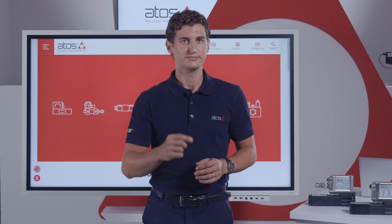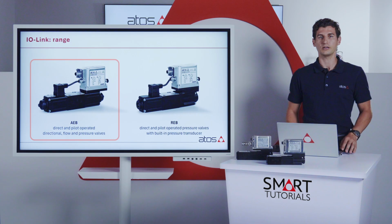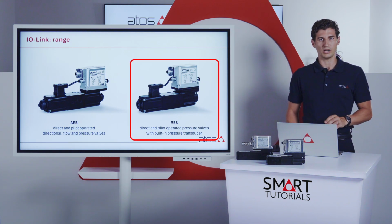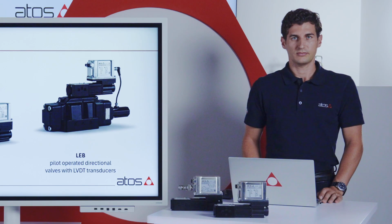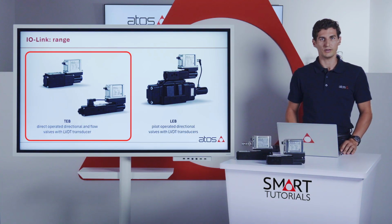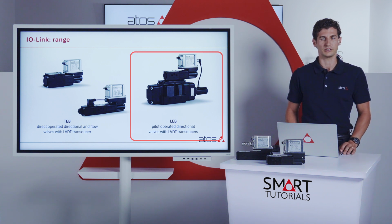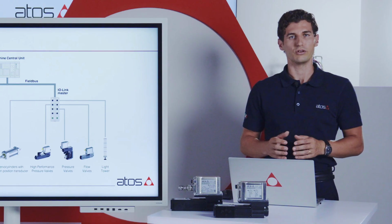So, let's start. The IO-Link communication interface is available for direct and pilot-operated directional, flow and pressure valves, and pressure valves direct and pilot-operated with built-in pressure transducer. IO-Link is available as well for directional valves and flow valves direct-operated with LVDT transducer, and pilot-operated directional valves with LVDT transducers. Now let's take a closer look at the architecture of an IO-Link system.